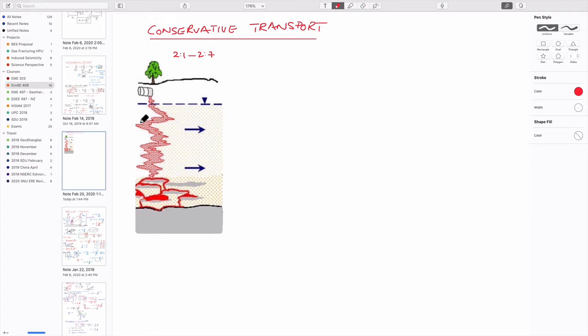But ultimately, we end up with some system that looks like this, and this is our source. It's basically a source for dissolution. Depending on the distribution of these saturations, which we'd expect to be quite small in this chimney, maybe 20% NAPL is left there as an irreducible smear as it goes down. And maybe it's close to 80% in these lenses.